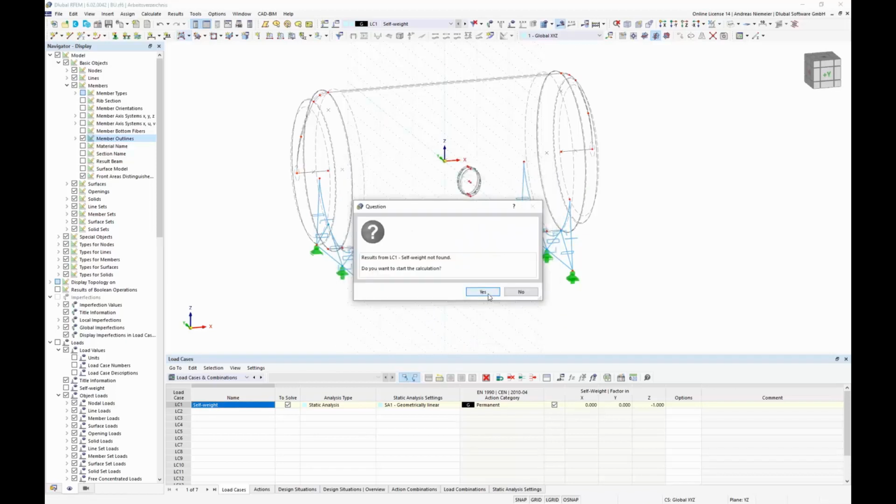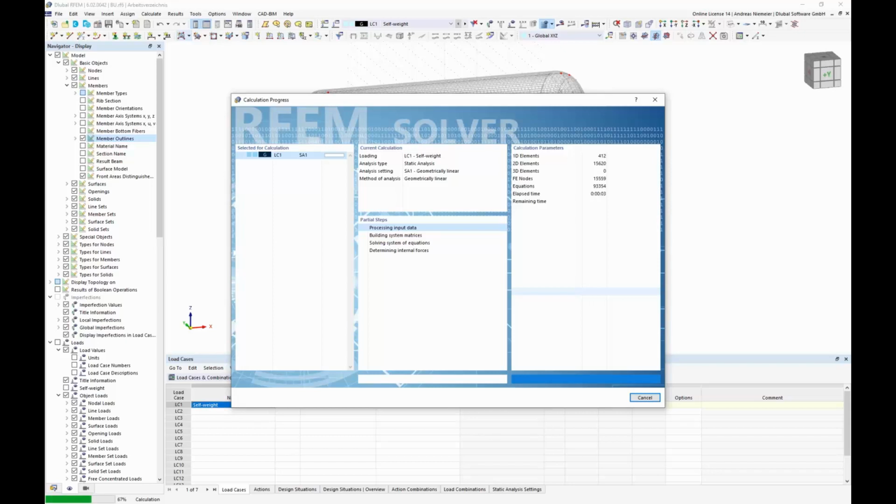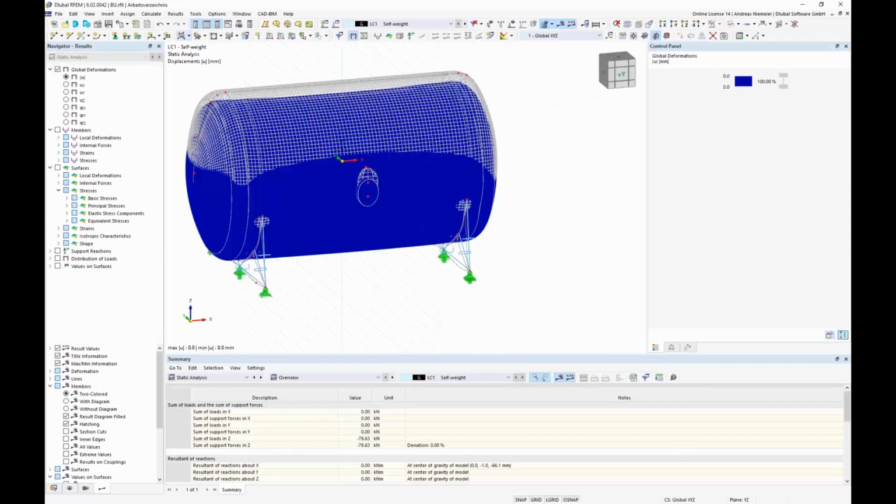And now let's run the surveyed load case because it's one of the best plausibility checks. If this load case is running, you know meshing is possible, you know you have supported everything, and if the deflection is also in the range that is expected, then you see also your loads are fine. But anyway, when you do load case calculations, I recommend also checking some result plausibility.